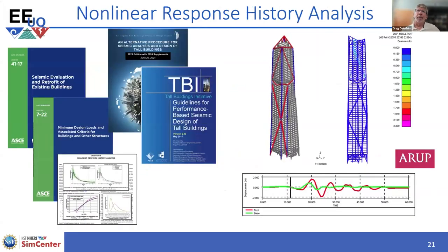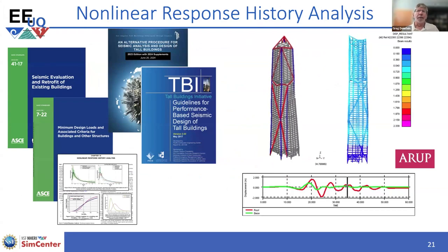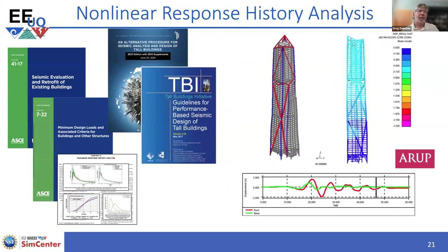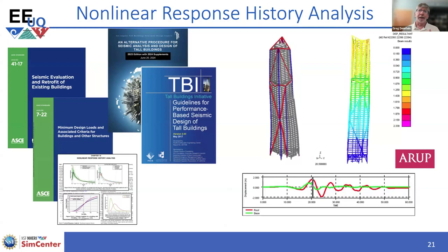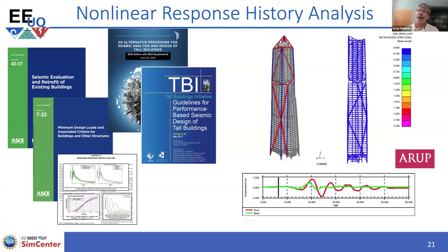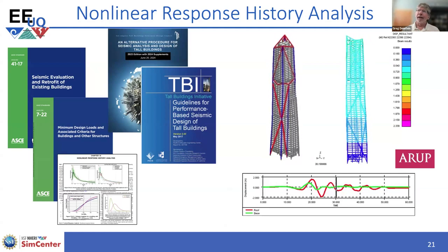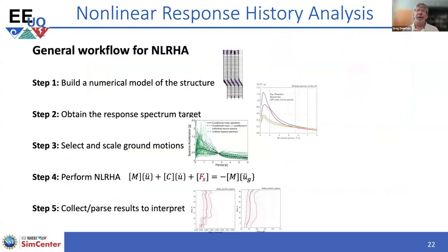Okay, so that was the one example. The next one I want to talk about is how we used EE-UQ to do nonlinear dynamic analyses. For me, the motivation is that in engineering practice over the last 10 or 15 years, nonlinear dynamic analysis has gone from a research tool to one that engineers are applying for special cases. The documents shown on the left outline procedures. In fact, tall buildings on the west coast of California routinely get a nonlinear dynamic analysis nowadays. So that was the motivation for bringing this into the class.